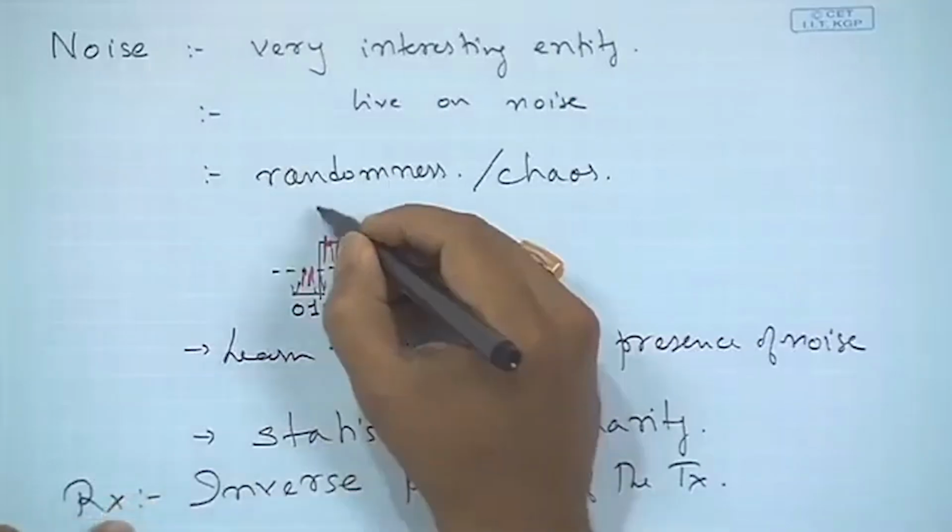I have told you in the introductory lecture, if you have gone through it, that in a digital communication system the receiver plays a very important role, where there has to be a synchronization entity, which synchronizes the carrier, which you may have studied in analog communications as well, carrier recovery, followed by timing synchronization, because as you are seeing here, time is a major factor.